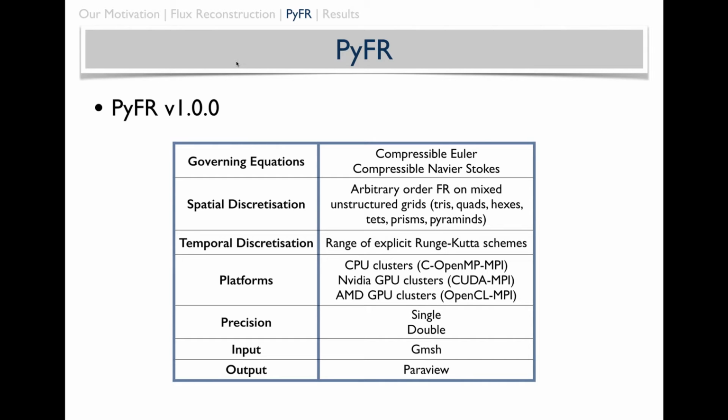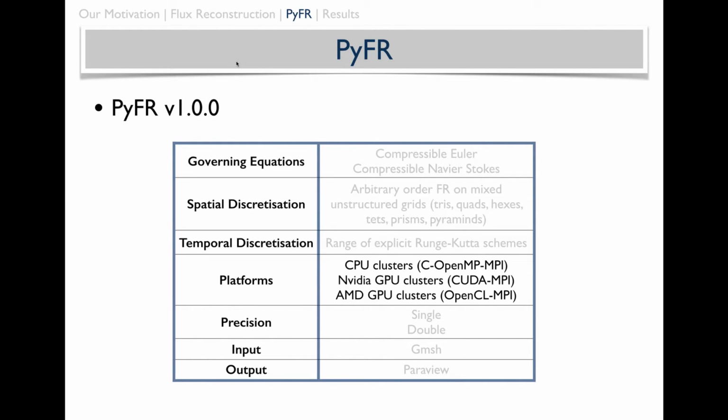We can take the gradient, or in multi-D, the divergence of this flux at each solution point, and we now have the semi-discrete form shown in the top right-hand corner of the screen. So we have the divergence at each solution point, and by a suitable temporal integrator, we can update the solution at each solution point to the next time level. That was a very brief overview of how flux reconstruction works for a simple 1D scalar system. We can extend this to multiple dimensions and to more complicated systems.